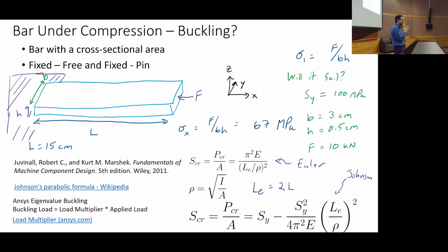It's 64. Well, it's pi d to the fourth over 64, yes. Or it's pi r to the fourth over 4. So that's usually the one that I use in mechanics of materials. It's the pi r to the fourth over 4. And then J, which we use for torsion, that is pi r to the fourth over, okay, or would be over 32, if you're doing D.